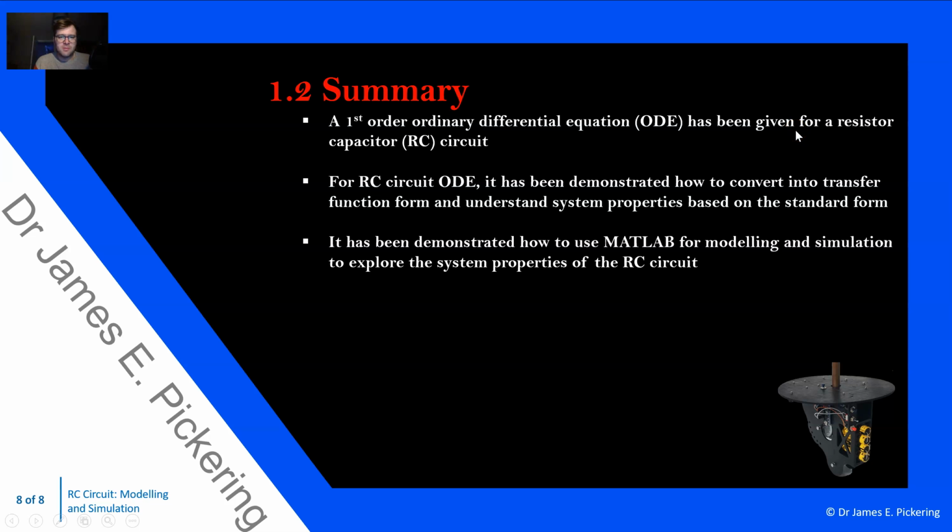So in summary, a first order differential equation has been given for a resistor capacitor, RC circuit. Go away and read up more on that circuit if you want to do so. It's demonstrated how to convert this into transfer function form, and then how to understand the system properties based on the standard form. In this particular case, it was looking at tau is equal to RC, and how this corresponds to the system response, and different values will give faster or slower system responses, i.e. charging of the capacitor. It's been demonstrated how using MATLAB for modeling and simulation can be used to explore the different parameters of the RC circuit, so effectively the time constant.